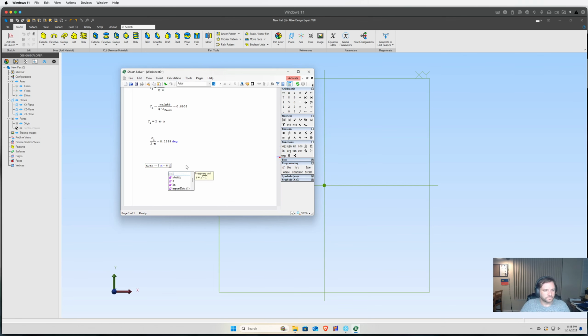And so we'll just show that here with inches, if I can remember my shortcuts. And there we go. Boom. So it's 39.4 inches roughly wingspan. And we have the area of the front. So we'll take the area of the front and divide that by the span. And that'll give us effectively how big the chord will need to be. And we get about 4 inches. So, okay, that's fine. So we have a wing with a chord of 4 inches, and a width of almost 40 inches, about 39 inches.